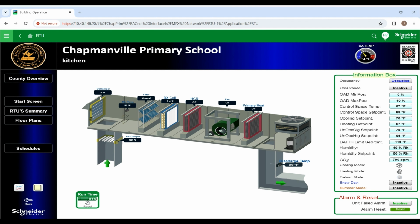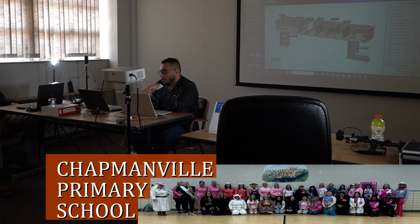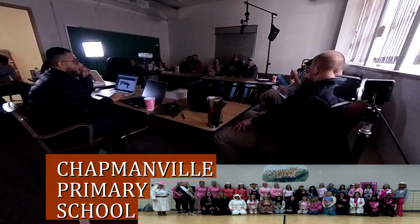override those. You have here on the information box a minimum position and a maximum position. If you want to shut your damper without overriding anything, you just change your set point to 0. But you have to restore that. I mean, you don't just change it to 0 and go away from it. Is there a summertime mode to this?